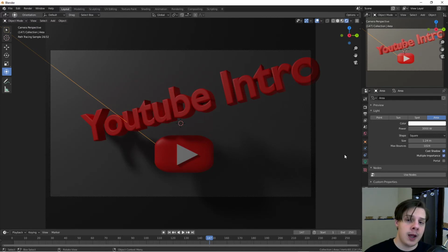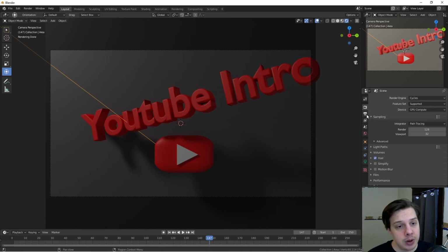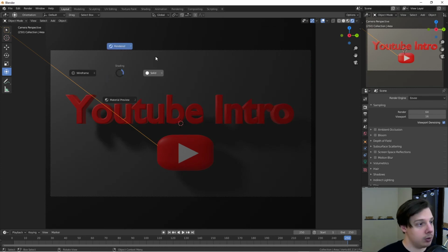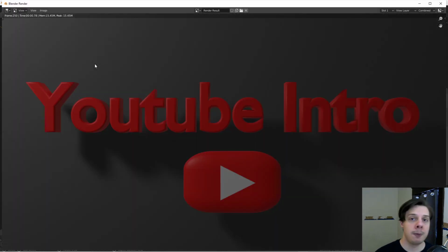Now, if your computer will take way too long to render out in cycles, which I would say way too long is anywhere above 8 hours, then you want to go and select Eevee. That is the render preview. So now we're just going to go to solid, and we are going to go to render image. So that took less than 1 second.